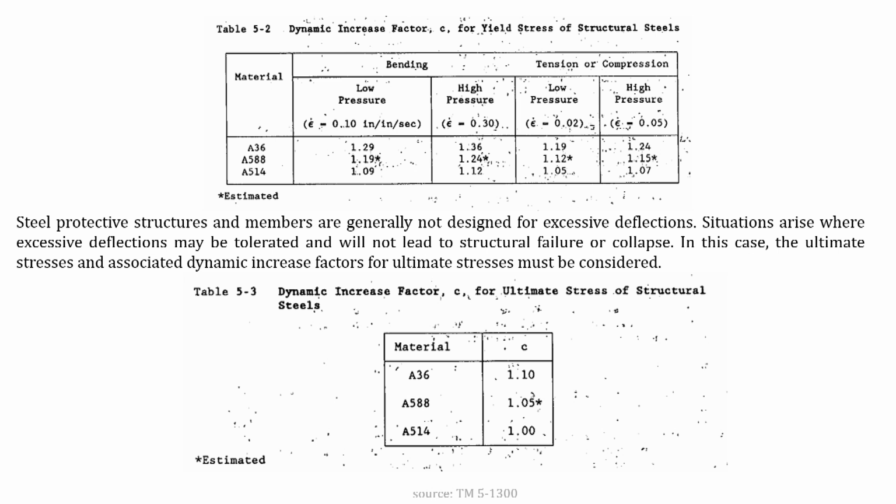the design purpose. Here we are looking at different types of material. A36 simply means that the yield stress of this particular steel is 36 ksi. These are the different nomenclatures of the steel, where this symbol normally denotes the yield stress of the steel.